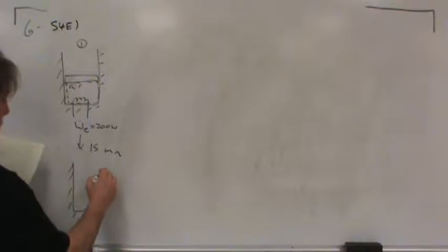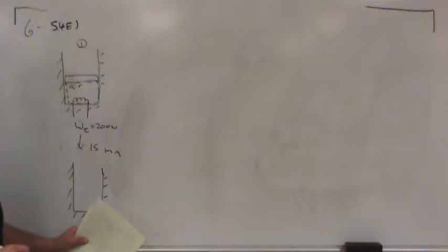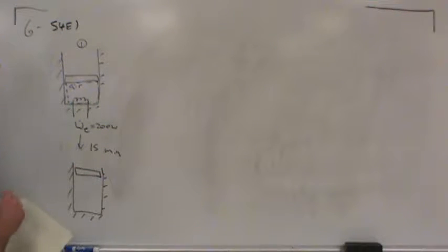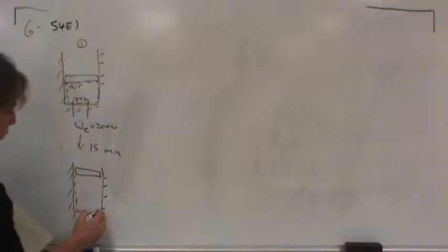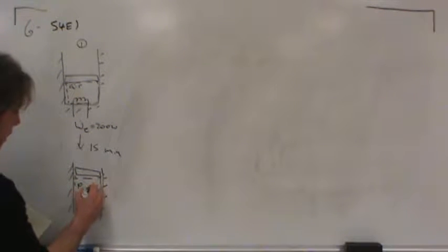And of course, what's going to happen? What do you think is going to happen if you turn on the heater and put energy into the air? Air's going to heat up. The air's going to heat up, it's going to expand, right? So you expect the piston to be moved up because you'd expect this to occur at constant pressure. Now the pressure in state 2 is the same as the pressure in state 1.